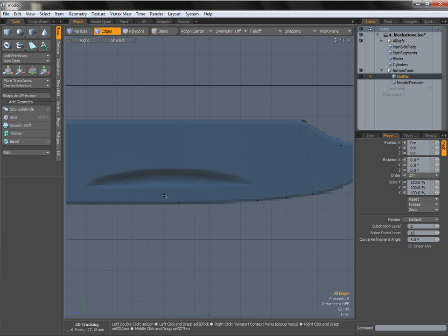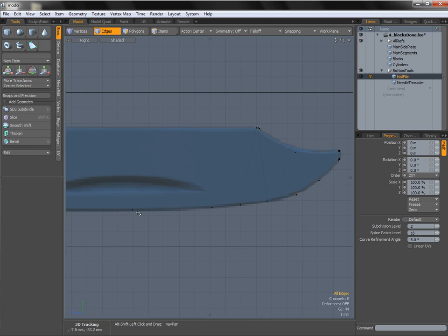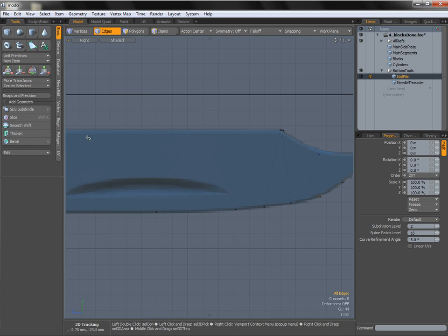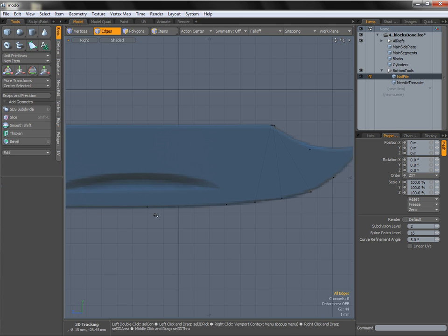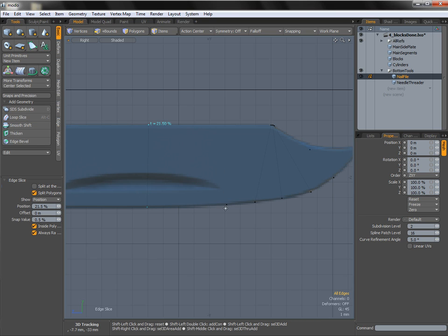So just like over here, just like before, all we need to do is add in an extra support edge to the left of this vert, which will stop it moving left, and it will keep that curve at the length that we want. At the moment, however, we just have some of these floating verts here on this giant multi-sided polygon. So the first thing we're going to do is split that up slightly with the slice tool, which is C. I'm going to come in and quickly drag a new edge to the top like that. It doesn't particularly matter where it is right now. I'm going to do the same thing, so I'm going to hold down Shift to reinvoke the tool, drag out to this vert, and then pull it up to the top like that.